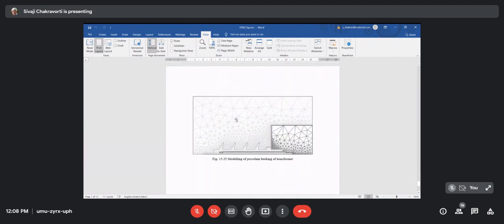In the same way here, from the porcelain, how far will I go? Otherwise, the number of nodes will be infinity. So here we have again brought in a fictitious boundary. Here you can see my mouse moving, and we have assumed that fictitious boundary condition. This is something we have to bring into our field computation, otherwise you cannot compute.